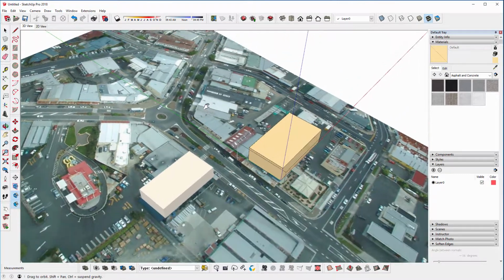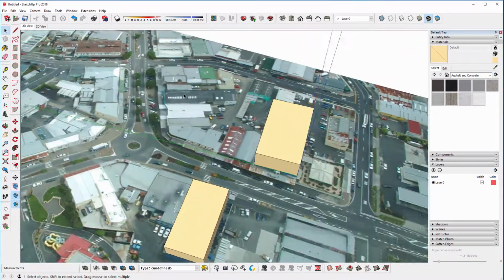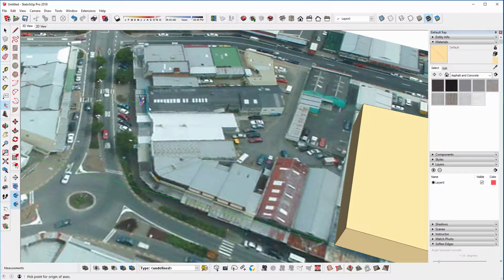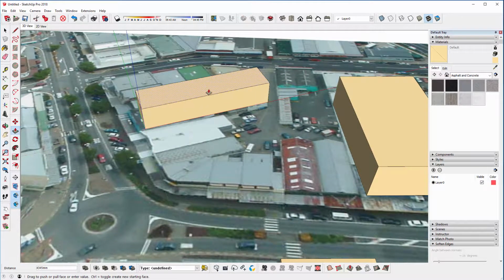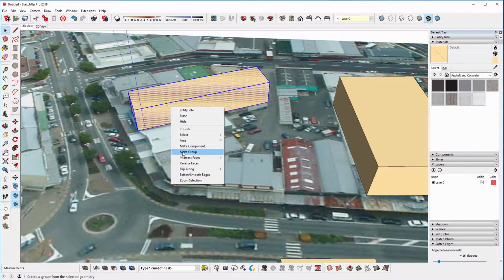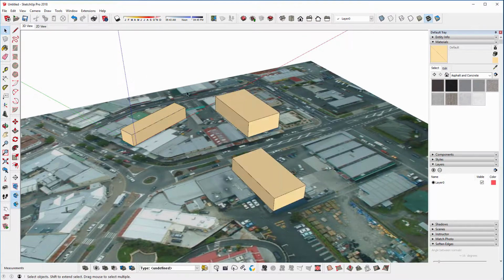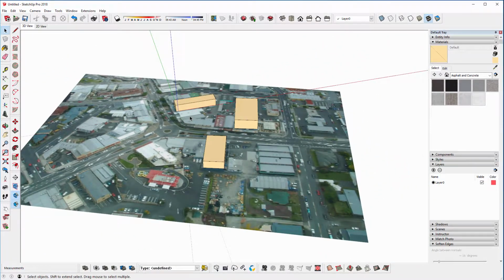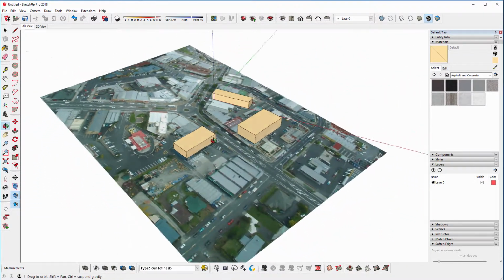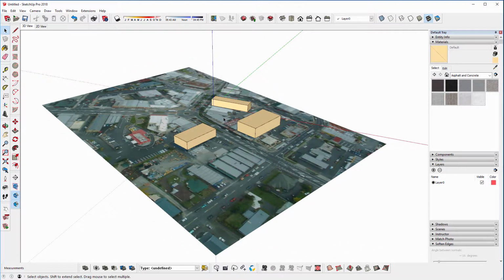So even the most interesting angles, we'll do one more. Get the axis tool, go along that edge, and I'll do a real rough one. I'll just push pull that up. Make it a group. So when I double click on the next group, you can see it remembers the axis. Double click on the one that I just did and it remembered that. So you can quickly go into models no matter what angle they are and be on a correct drawing axis.